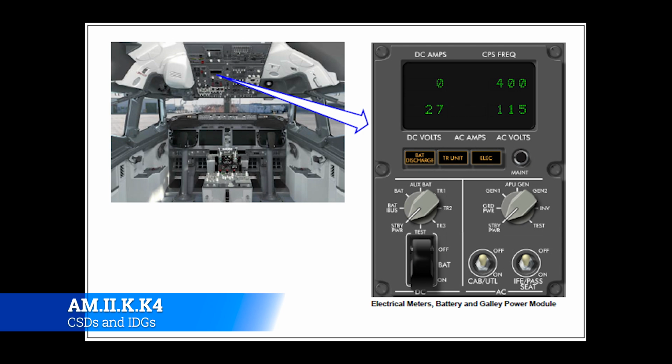And so that means they know that, hey, look, our batteries system should be driving this type of power. Our standby power system should be driving this type of power. TRU 1, 2, 3, whatever. It should all show this type of power, because they know that some of these systems will throw faults if they're underpowered or overpowered or there's some kind of problem. So it's a really good thing to do to start playing with that system right then and there.